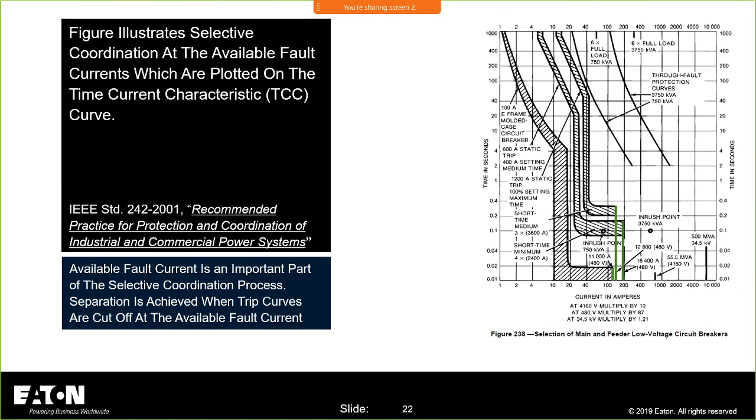These curves that you see here are the transformer damage curves. What's not shown here is that most often we'll put the damage curves for conductors, and those look basically like a straight line like this. That's a terrible straight line, more like 4 or 5 straight lines. But in any case, you'll see a line somewhere on here that represents the damage of that equipment.